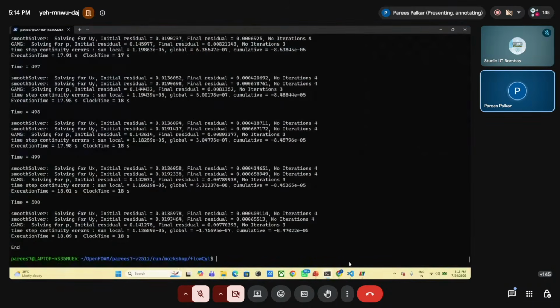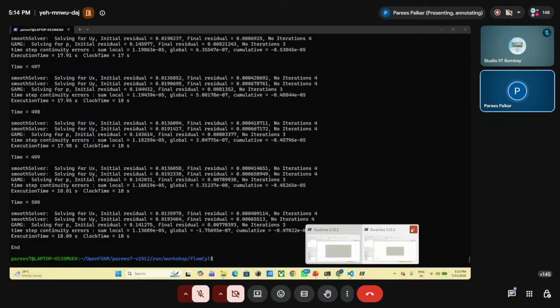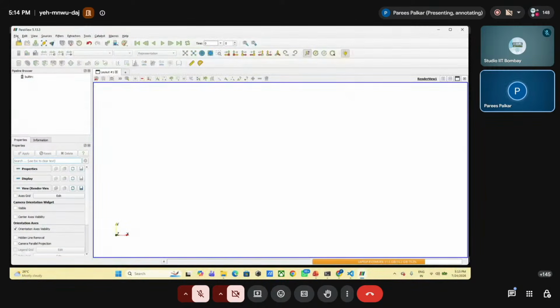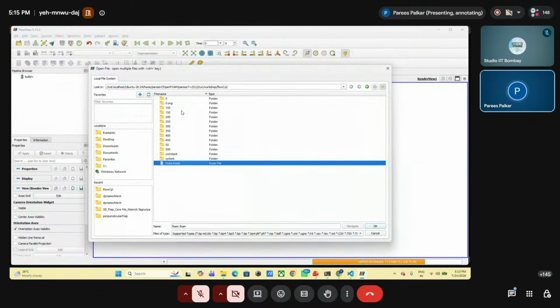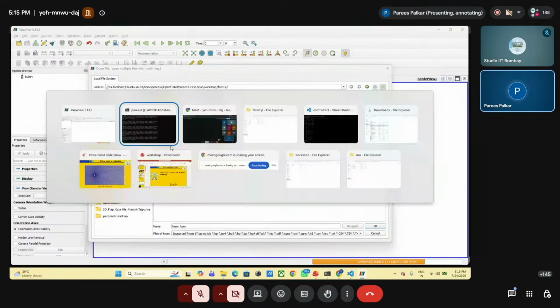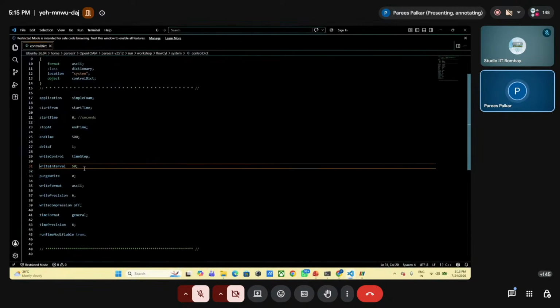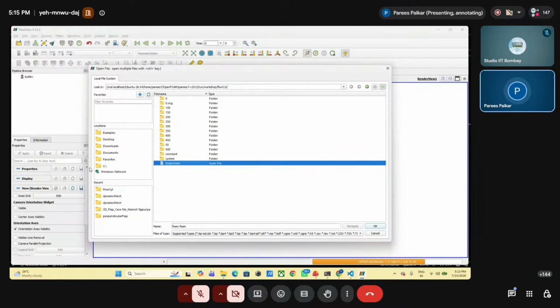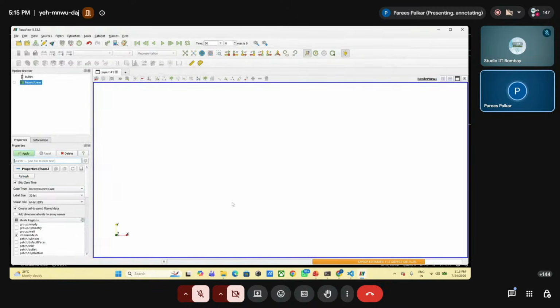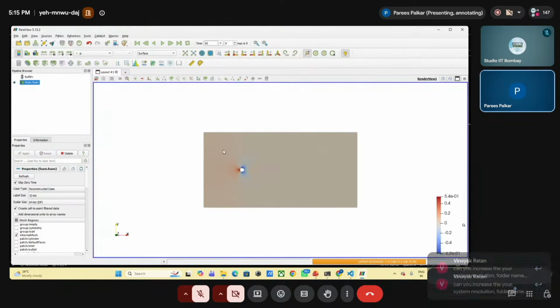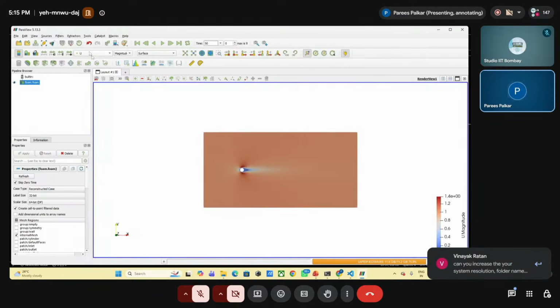Okay. Now, I'll go inside one of the ParaViews and delete it, and I'll load the foam.foam folder. Now, if you can see, it has stored every file at every 50 iterations. Why? Because I had changed this write interval to 50. Previously, it was 10, but now I have changed it to 50. So I'll just hit OK now and hit apply. Inside the properties panel, there is a green icon called apply. I'll just press apply. So I'll change to maybe pressure and I'll switch it to 2D.